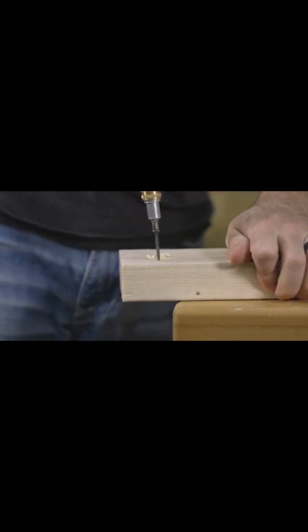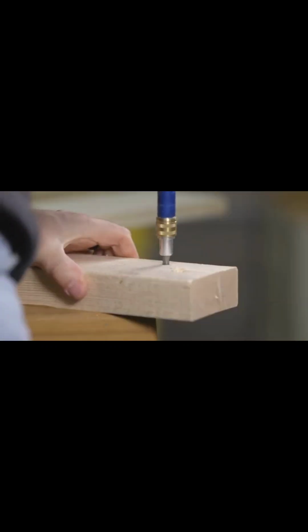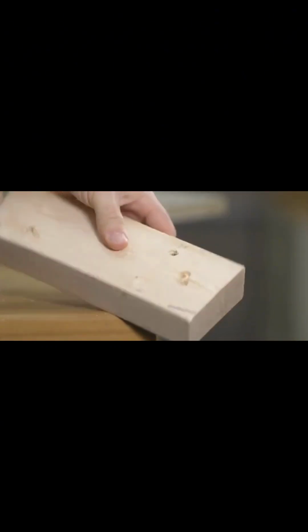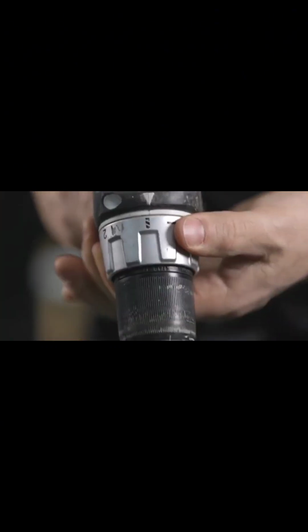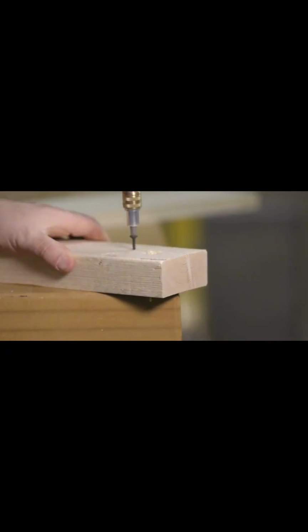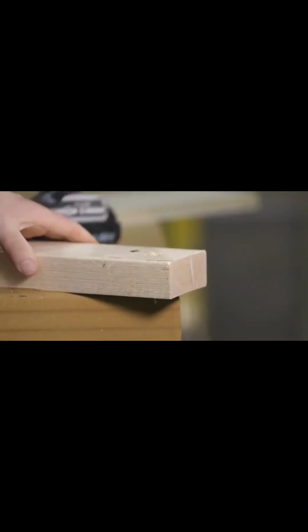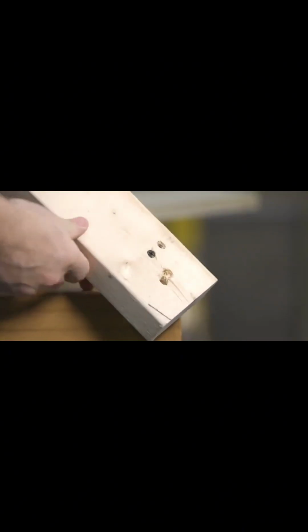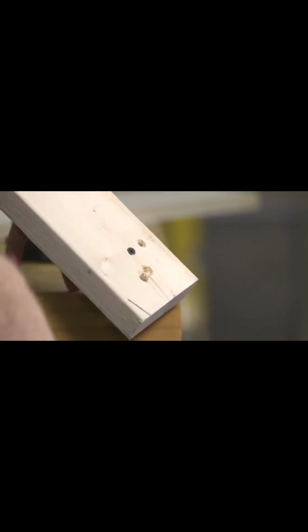But if you were to use that same setting for screws, the drill could drive the screws too deep, especially if you weren't paying attention and controlling the trigger properly. This time, if you adjust the torque to a lower setting like an 8, the drill will only provide that level of torque before slipping the clutch and stopping the screw from sinking any further. You can see how this would be helpful for setting screws at a specific depth in different types of materials.